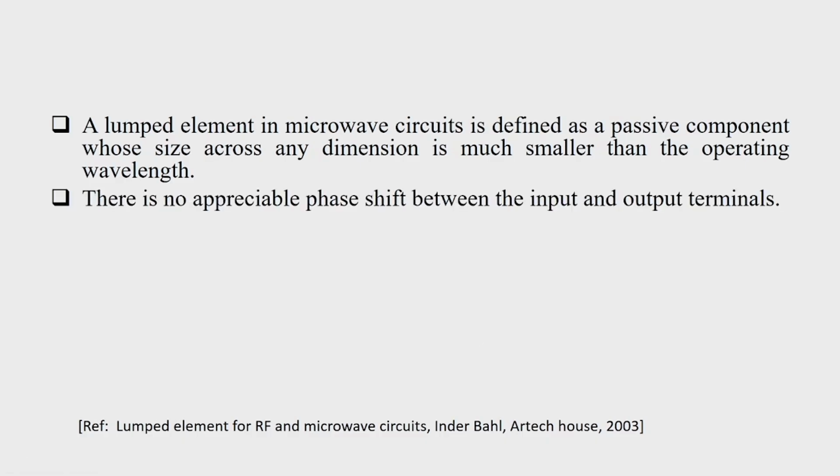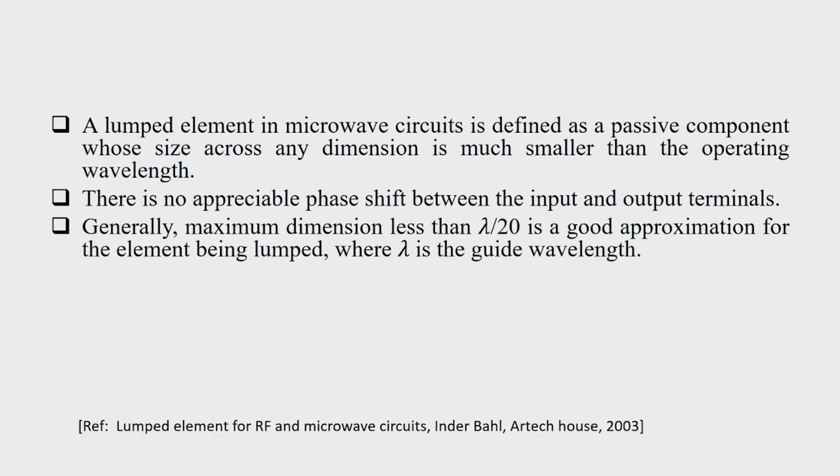There is no appreciable phase shift between the input and output terminals of this type of lumped element because of their small size, and generally maximum dimension less than lambda by 20 is considered a good approximation for the element being lumped, where lambda is the guide wavelength.